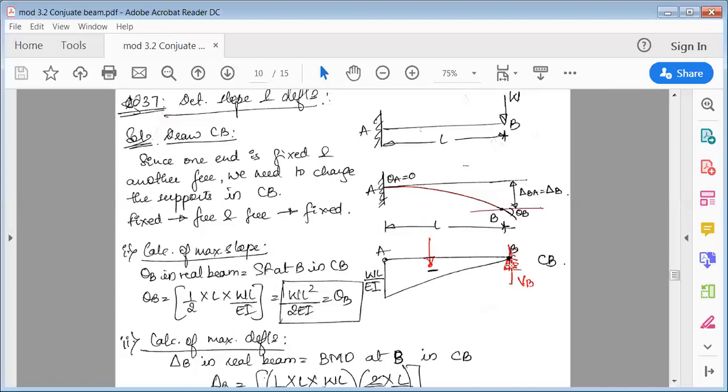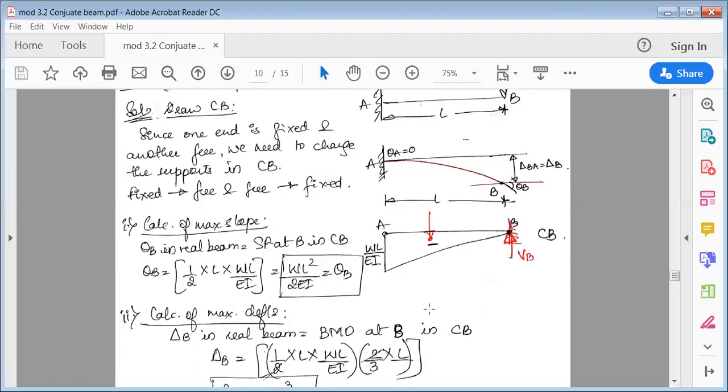Okay, the main matter of interest is vertical forces only. So we're ignoring horizontal force and moment, and only show vertical forces. So we have to find out this vertical force. To find this vertical force, it is the area of this diagram, the M over EI diagram.